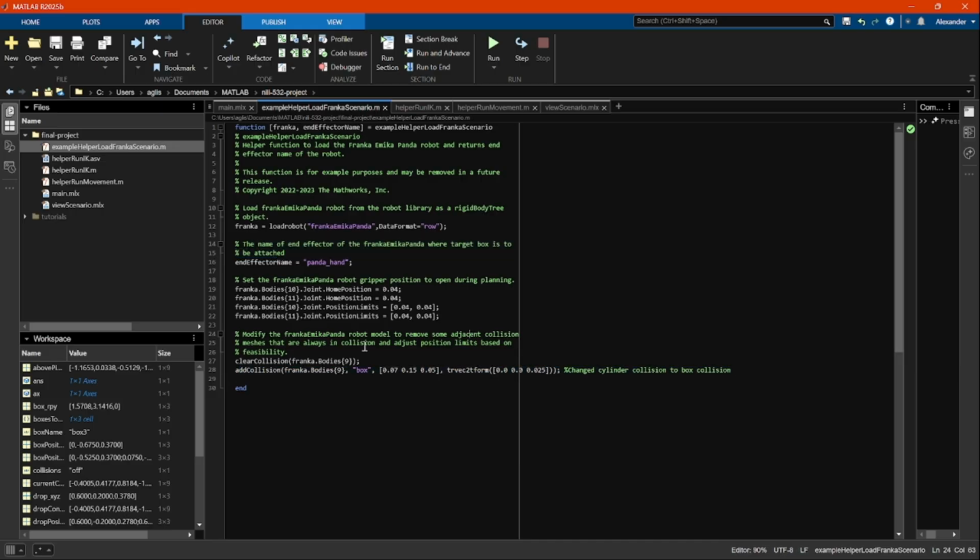But the way they solve it, I actually needed to change it back. What they did was there was a constant self collision between the final link and the second to final link, so that it would always throw an error and always think that it was in self collision. So they responded by changing the geometry of the collision mesh to a rather large, oversized cylinder.